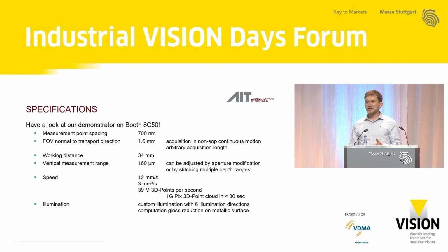From the working distance, it's actually quite far away, which is good for industrial applications, so you don't have to be super close to the object. It's 34 millimeters. The depth measuring range is 160 micrometers. You could adjust it to your needs with sacrificing optical resolution. You could also get a better optical resolution by decreasing this depth range,